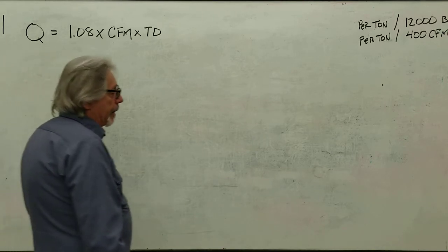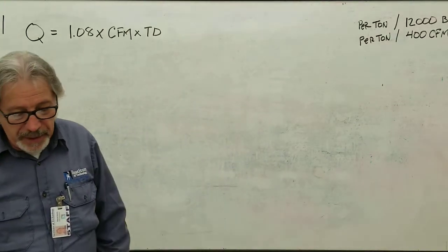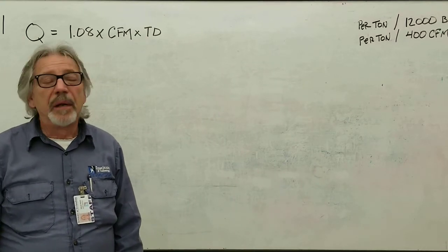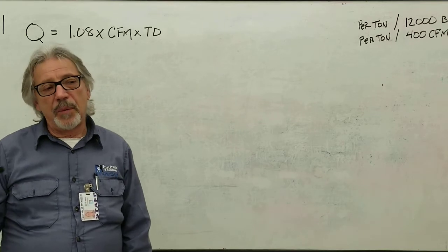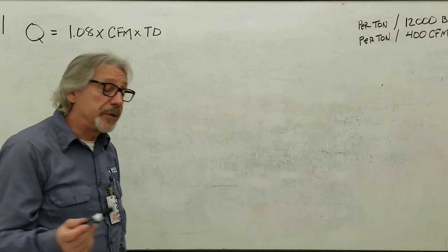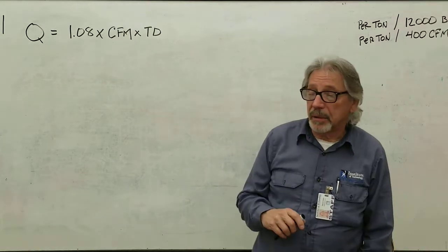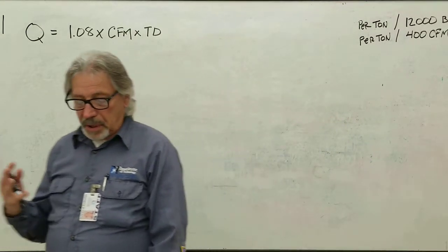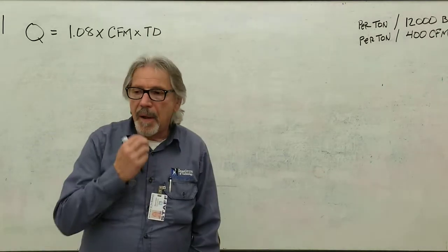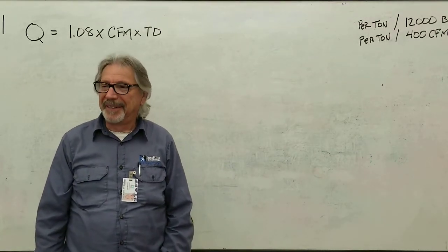But if you're talking about heating in fossil fuels or in butane, propane, they wanna reduce the CFM for the heating cycle. So the blower speeds are turned down to medium or low, depending on the application. Can you give me a reason why we wanna slow down the airflow in heat?